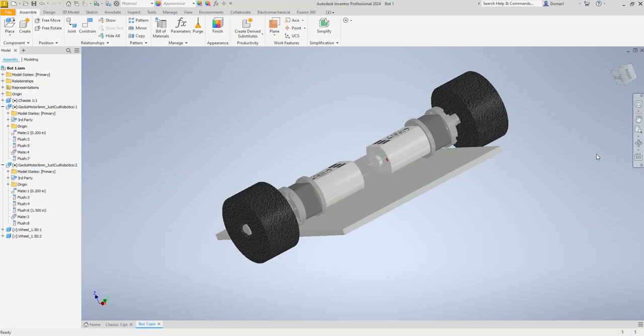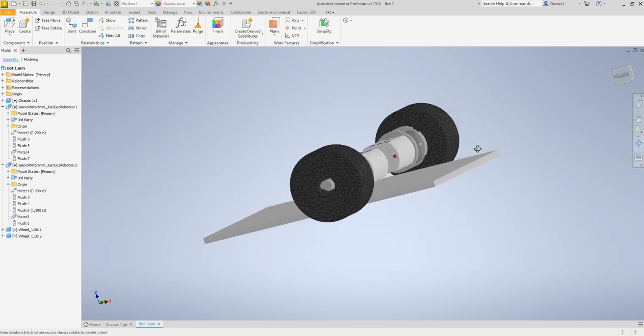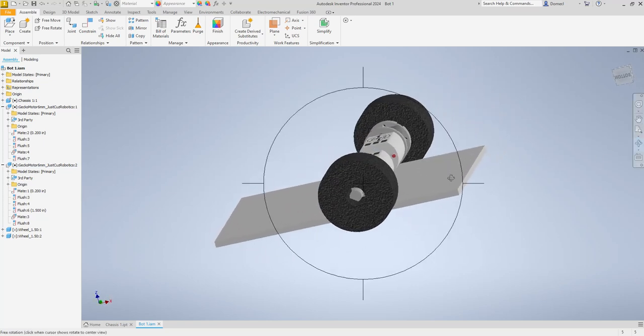I know if this is going to be a wedge bot, in general, I want the wheels in back as far as I can go so that the wedge is always on the ground. Think about it. If I put these wheels in the middle of this plate and I drive, what's that bot going to do every time I drive forward or backwards? If they're in the middle of the robot, it's going to lift up, right? Like a teeter-totter. Every time you go, it's going to want to cock up on that. But if I get those wheels all the way back and you've got the weight forward, there's less of a chance of that thing doing wheelies as it drives. I'm not saying it can't, but less of a chance.